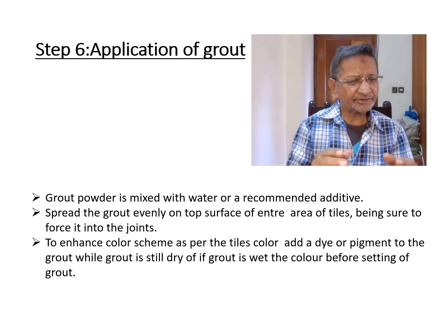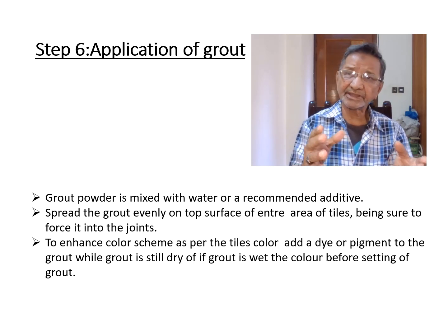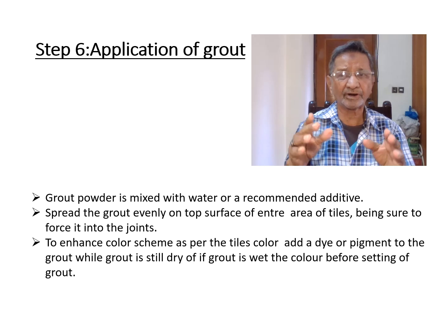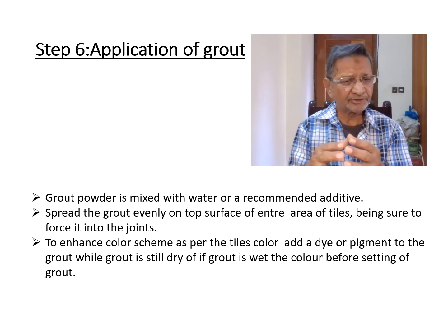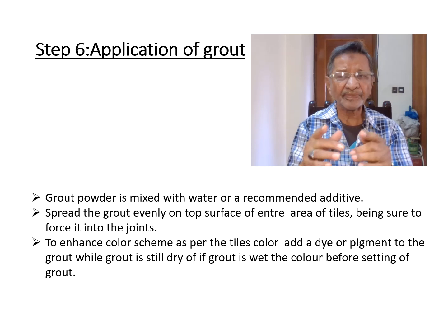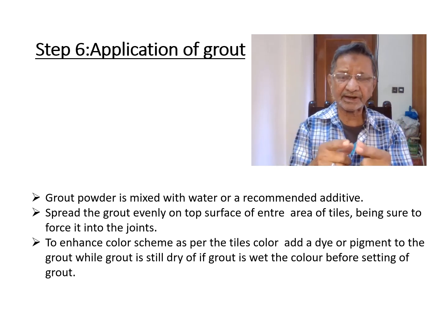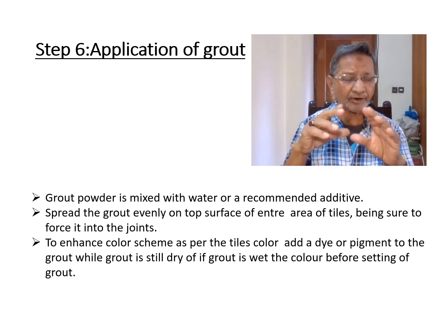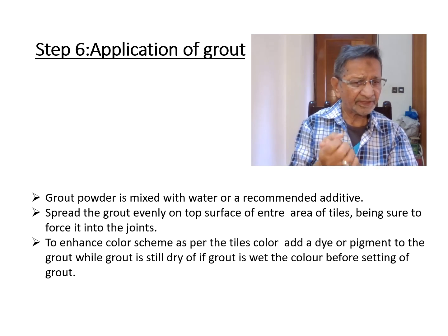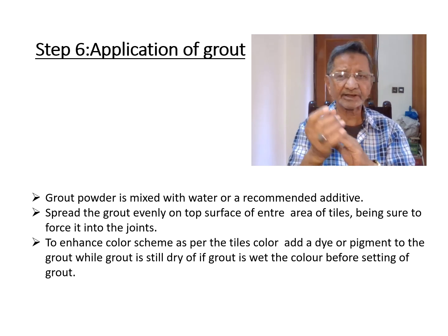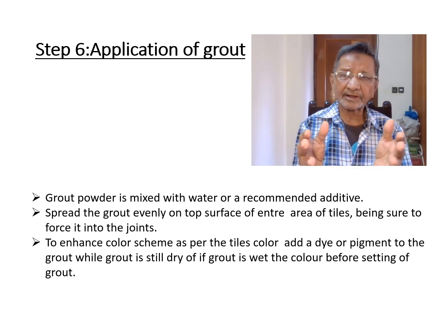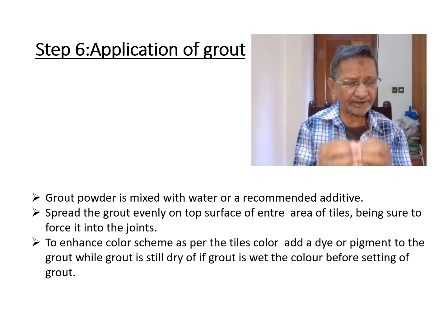To enhance the color scheme, I mean, as the architect is advising or as per the drawing, you have to maintain the color scheme according to the color of the tiles or as specified. So this color scheme is important. The grout should be of the same color as the tiles or as approved.